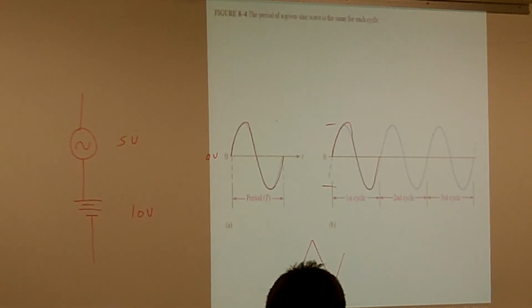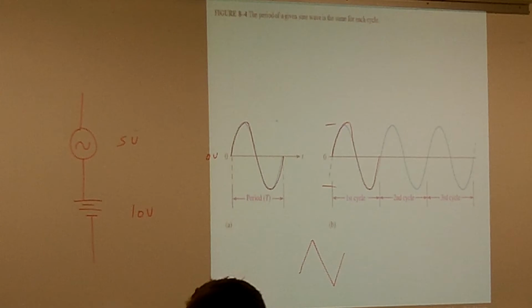So what happens is that my AC signal, my amplitude for this particular one, is going to be going to a positive 15 volts and then going down to only a positive 5 volts. Okay? So it never changes direction, it never changes polarity, right? It's just varying the voltage between a positive 15 volts down to a plus 5 volts, but we still consider it an AC signal.